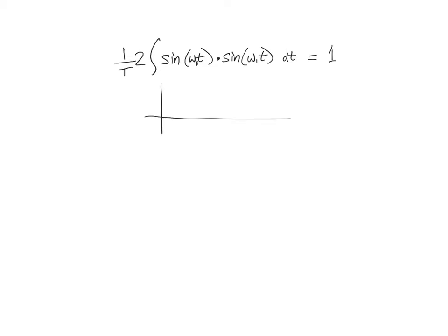The reason for that is that if you have a sine wave that's going like this, and then you square it, you get a wave that's going like this, and you notice it's got a DC level to it. And the average of that DC level over long periods of time is a half. But obviously if I integrate over long periods of time, I'm just summing a half again and again and again, and I need to divide by the amount of time that I had to return this average. Okay, so that's the fact number 1 that lock-ins exploit.